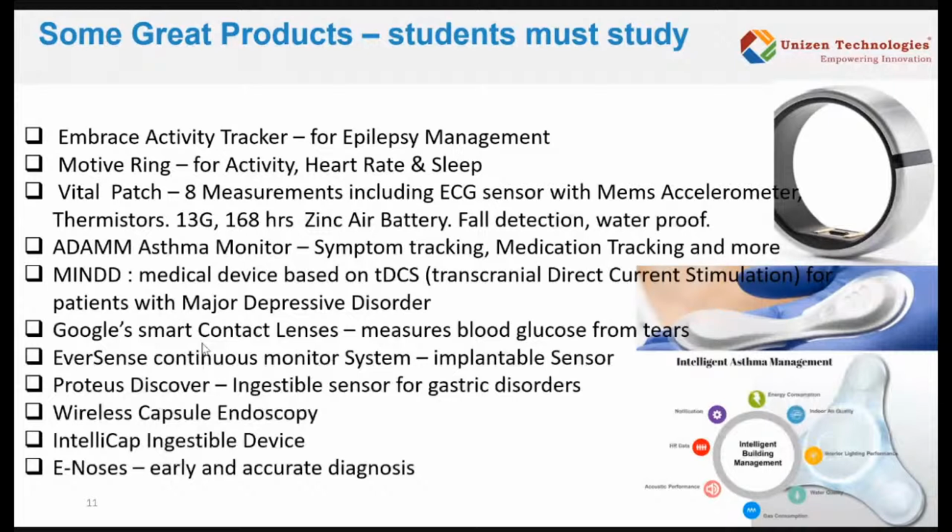Okay, so just to tell you the complexity, 2.2 millimeter thick includes the PCB, its components, the band and gel material which is put on both sides, and the battery. Out of that, the battery is 0.8 millimeter thick and the PCB is 0.2, so that itself is 1 millimeter. So we have 1.2 mm to put all the components in. So the component selection should happen in such a way that every component you have selected should be less tall than that. See, to add to that, there is one more complexity.